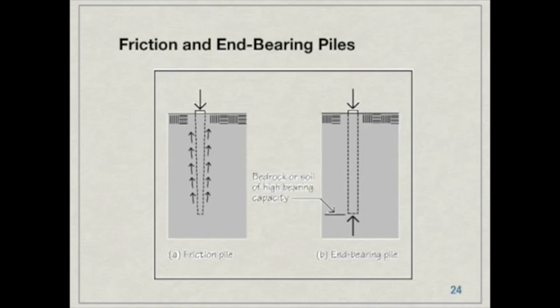Now how we select our piles and where we're going to use them is going to be a function of several factors. First and foremost is probably going to be availability, and then we also have the cost to deal with, and then the below grade environment. Obviously steel can corrode under certain environments, and concrete, if we're going to be in a soil that has heavy sulfates, we're going to have to use a type 5 cement. And if we have a moderate level of sulfates, then we're going to use a type 2 cement.